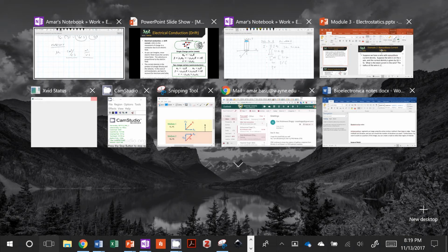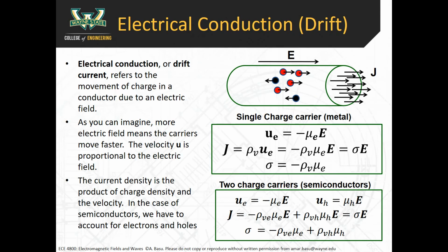When would you have wires that had different densities on the outside relative to the inside? Sometimes it happens when you're doping semiconductors. Semiconductor wires are often formed by a process called diffusion. This is where you start off with silicon and then you diffuse boron or some impurity in there, which makes it conductive. Since the impurities are coming from the top, the top of the semiconductor is actually more conductive than the bottom of it. So that's the situation where you may have non-uniform conductivity and non-uniform current densities.